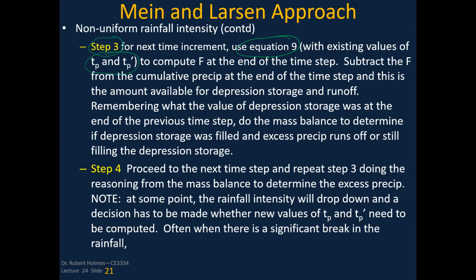There's a chapter in your references that's by Skaggs, who was at North Carolina State University, but he wrote in a textbook that I have called Hydrologic Modeling of Small Watersheds. And he shows some research, I can't remember the exact research paper that he referred to, but it basically said that the relation of cumulative infiltration to infiltration rate is very insensitive to the intensity of the rain.